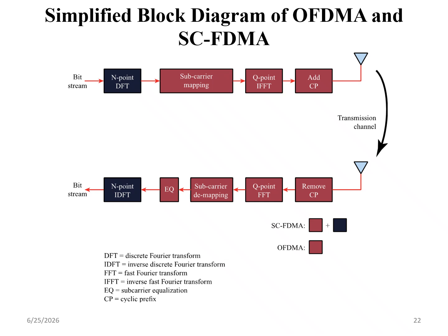That's all. Everything else we discussed in OFDM is carried out. On the receiver side, we add two changes. One is subcarrier equalization, then the FFT will be converted into IDFT. That was the technology.